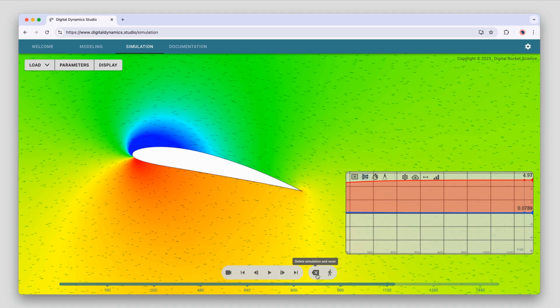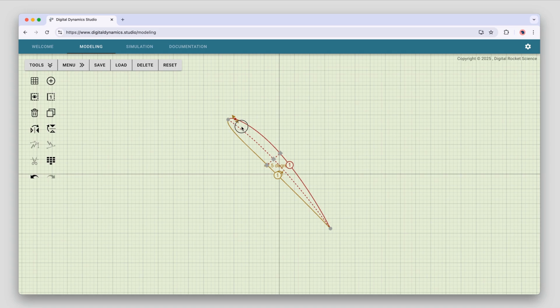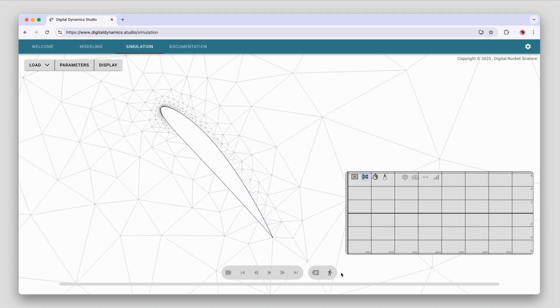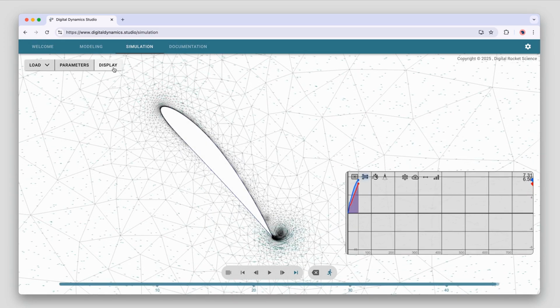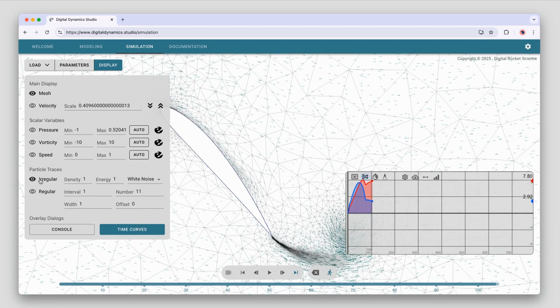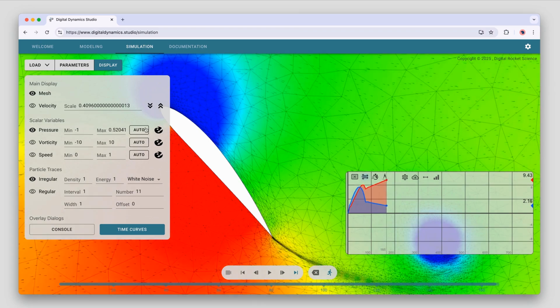But we should note that only goes so far. Once the angle of attack gets too high, let's say 50 degrees, it starts to break down, and the flow will separate, and the aircraft will stall. So this super high angle of attack of 50 degrees is not realistic. You'd be falling from the sky in reality if you're under this condition.